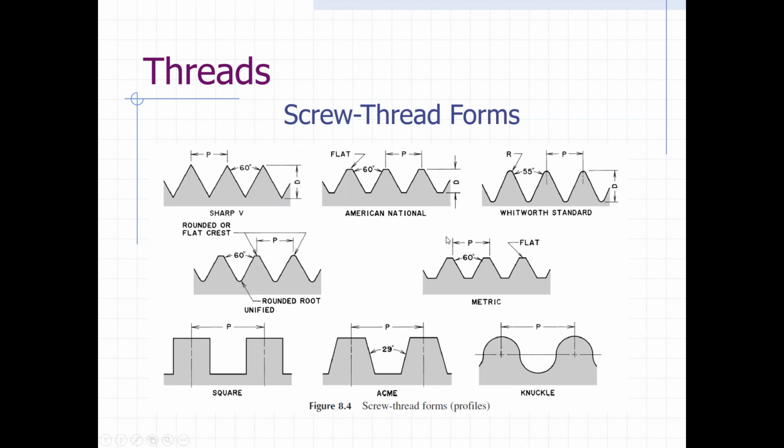Now, if you're working in Inventor or even some of the other packages, a lot of those packages might not have the Acme screw threads in the thread bank, right? It might not come packaged in the software. And in that case, don't panic or don't get too concerned, right? Which way did I say we wanted to represent our threads? Simplified, right? So that's just got the solid line and the hidden line. So what you do is you just put any thread that fits on that size cylinder on there, and then in the drawing call it Acme threads like you're supposed to.